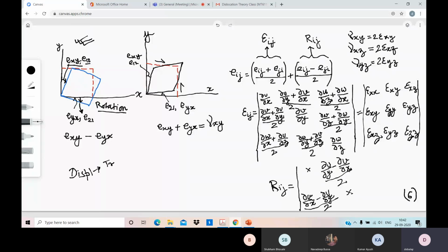And you will find that kind of displacement because the point x is moving into x dashed or p is moving into p dashed. But that aspect can be taken care of very simply by moving the coordinate along with that body. If you fix the coordinate along with that body, then with respect to this coordinate, there will not be any displacement or any change. So translation can be taken care of by simply attaching the coordinate with the body and moving the coordinate along with the movement of the body.